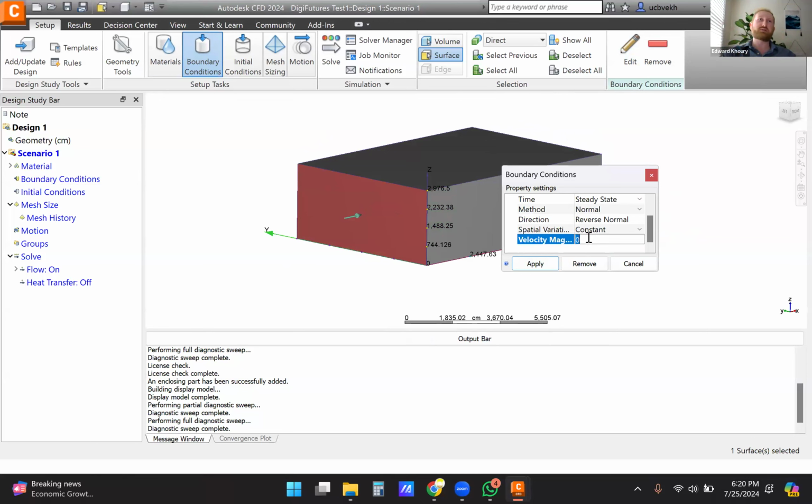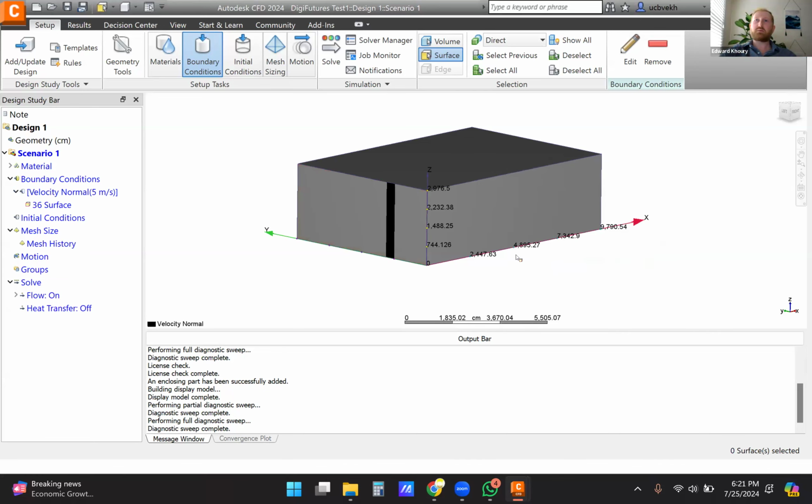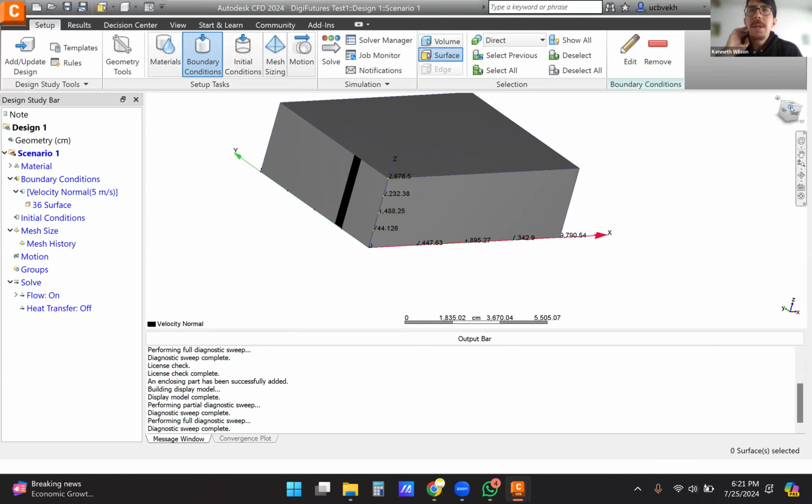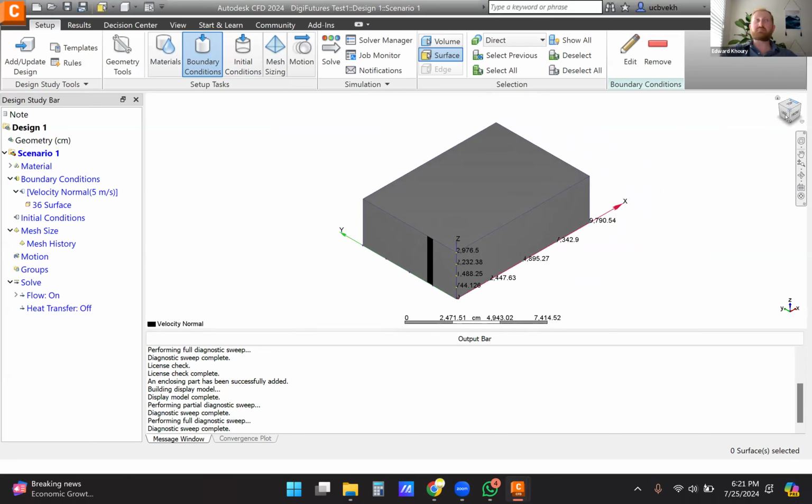Is it possible to define a vector for it? Do you mean the direction? Yeah. Usually the direction, the vector of the wind, is perpendicular to the surface that you put it at. But if you want a wind flow simulation that has a direction that's not perpendicular to your volume, you can just rotate your volume. Usually the box that you use as a reference works on perpendicular vectors. What can rotate is the geometry inside.